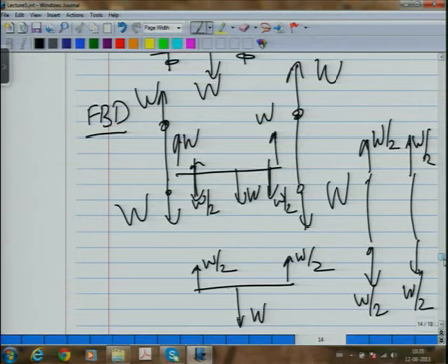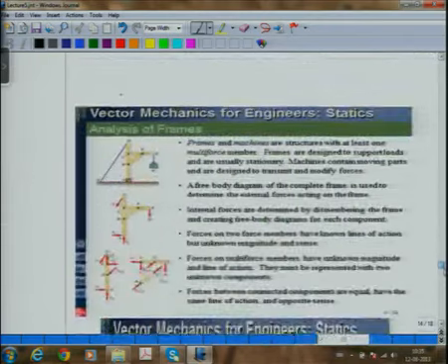And that is what caused the big failure. They thought that they were doing something good by reducing a column of such a big length to 2 half-length columns, but not doing a proper free body diagram and proper statics analysis led to the failure of this. So I have made a very simple analysis. Of course, when bolts fail we talk of shear failure, and these loads cause shear stress in the bolts, that I am not discussing here.